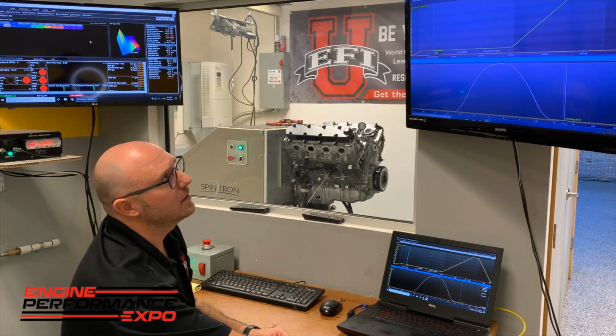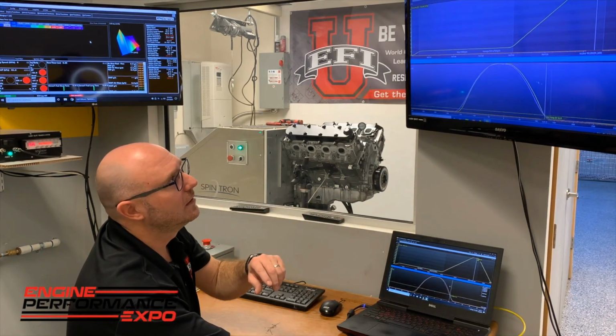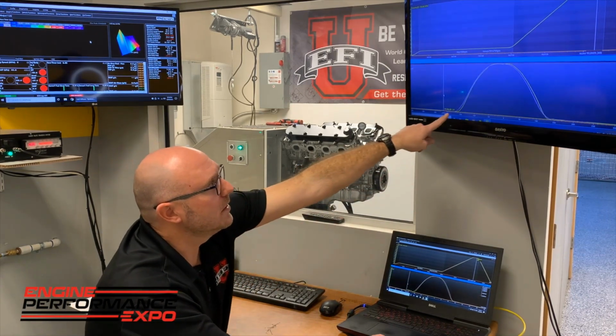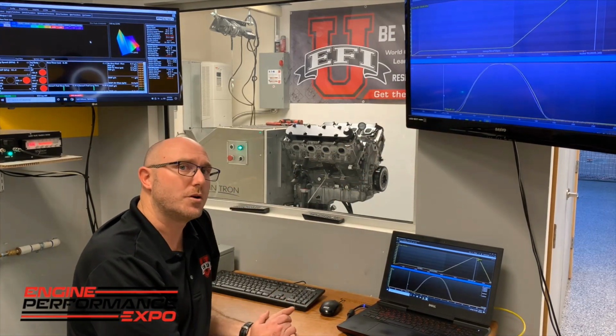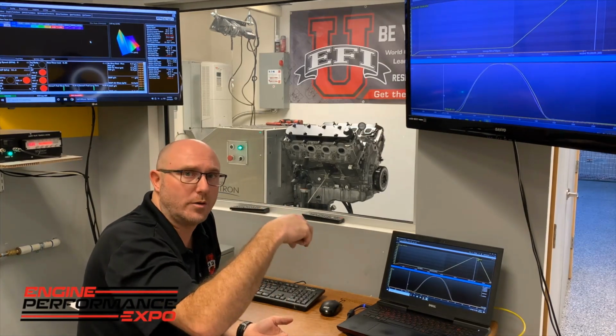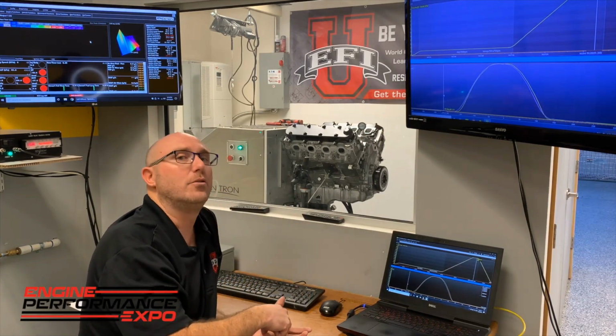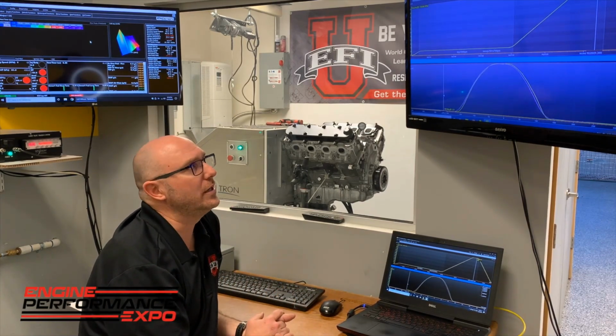The first thing I notice, and I do that, is darn it, sorry, I did that again. I come over here, there's a lot of bending and deflection somewhere. Now that could be a number of things. That could be my push rod, the rocker arm. It could even be the bolt that goes down through the rocker arm and holds it into the cylinder head, trying to pull the threads out of the cylinder head. There's any number of those things that could be doing that.